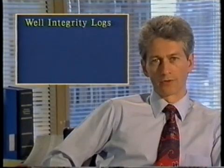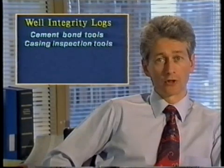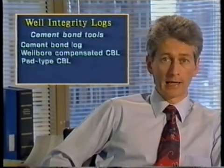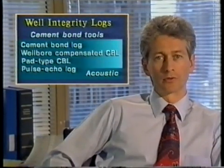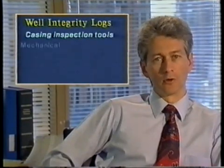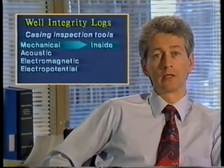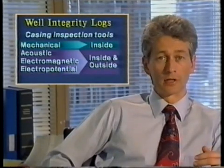Well integrity logs for the evaluation of cement and casing conditions include the cement bond and casing inspection tools. The cement bond tools include the cement bond log, the well-bore compensated cement bond log, the pad-type cement bond log, and pulse echo tools. All of these are acoustic devices which evaluate the amount of annular cement around the pipe. Casing inspection tools include mechanical, acoustic, electromagnetic, and electropotential measuring tools. Mechanical tools can make measurements only inside the casing, while the others are capable of evaluating both the inside and the outside of the casing.